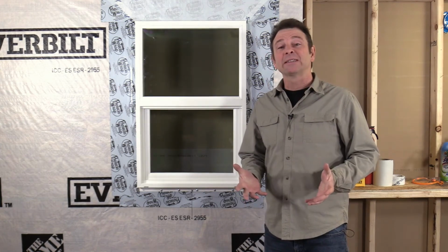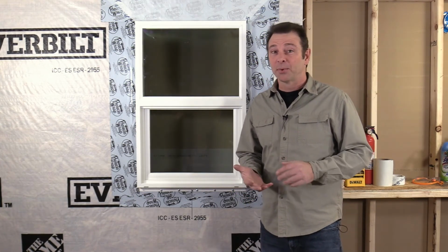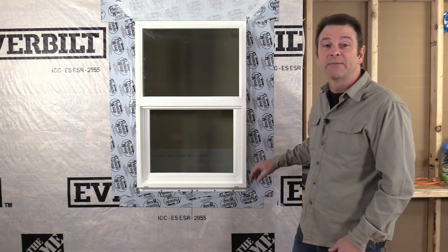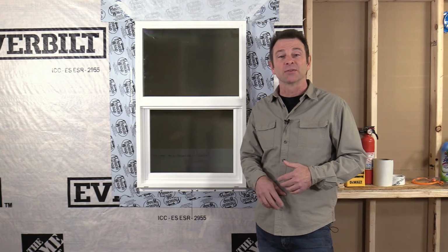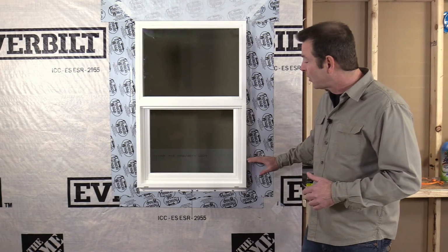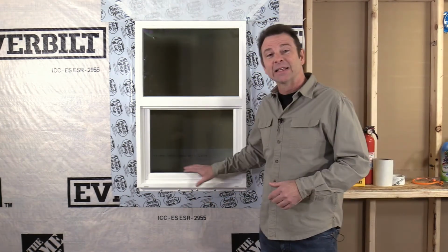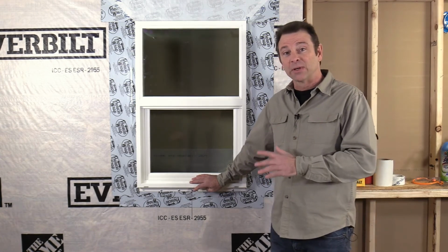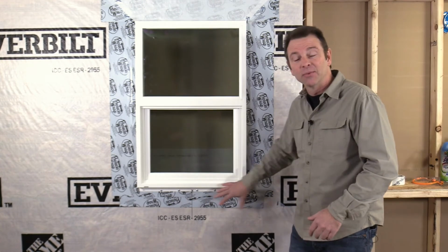The next part of the process is the sill pan. This is a major important component that will waterproof the bottom 6 inches of this rough opening. There's a number of ways to do it, whether that's with straight flashing, pre-formed flashing, or also a flex wrap that will flex in place, or you might see pre-formed corners used with a straight flashing. Any of those will work. The bottom line is we're trying to create a waterproof situation here. In case we get a leak in this window, we won't have problems with rot in our framing. And if a window is going to leak, it will be in this area right down here.